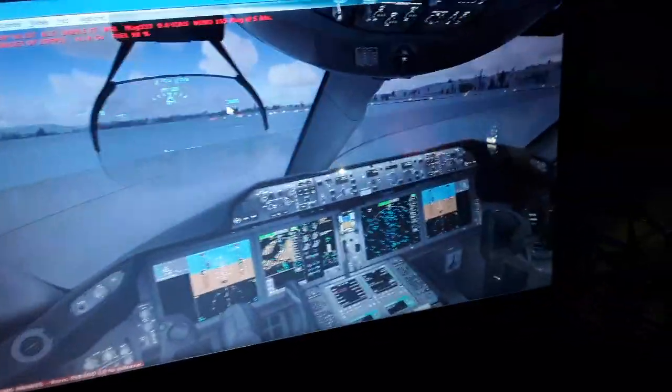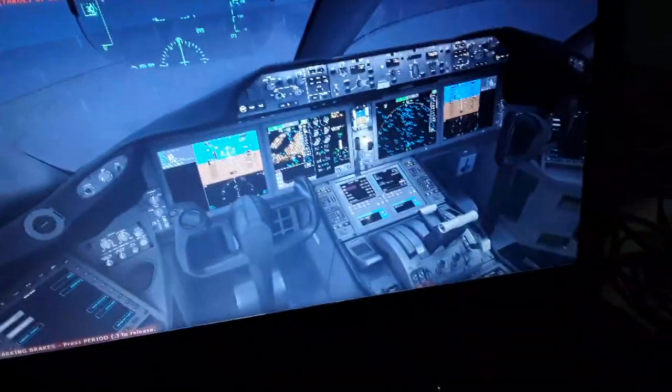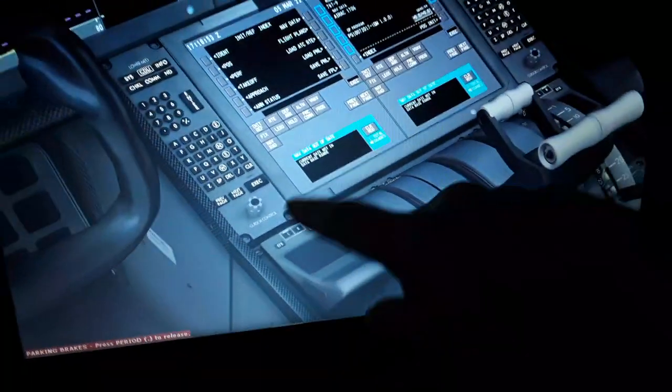We're going to have 25 to 30 degrees of flaps extended, 160, 170 knots of airspeed or 270 or 300 kilometers an hour. I'm going to approach and land with the landing gear extended. So you're going to see also the flight management computer I'm going to use for creating the flight plan. You can see we have the mouse pad here to input all the data of the aircraft for this flight. I'm going to use the mouse pad for controlling the screen that displays the flight management computer. I can also use my keyboard here, as you can see.